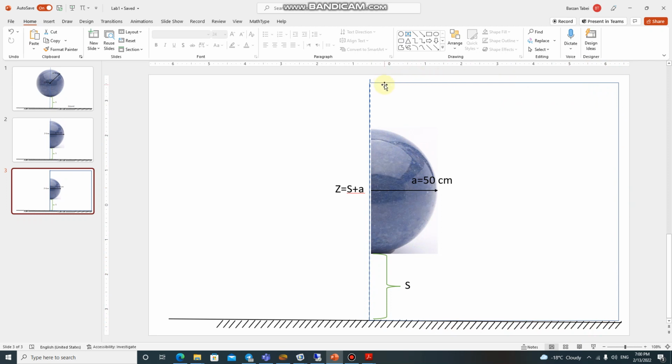In my calculation, I consider 5 meter as one side, but you should also consider 10 and 20 meters or whatever, and you should show the effect of increasing the dimension of this box on the convergence of the calculation and select a specific value.